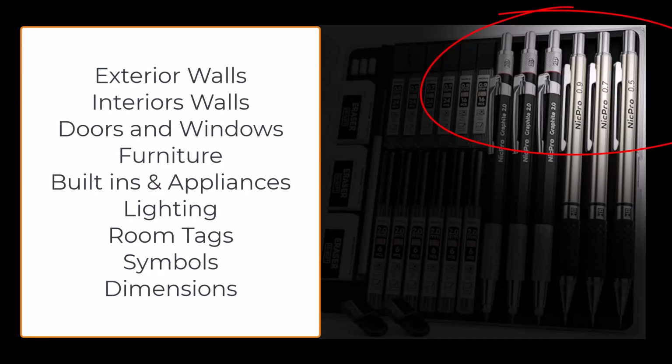What is most important about the pencil is that you are using the different gauges, which is the 0.3, 0.5, 0.7, and 0.9, and that you know what those lead types are as well. Some are softer, some are harder. They're going to be sharp, clean lines. So for instance, a 0.3, you want a sharper pencil because you're going to be creating very small, detailed lines. Those are the interior of a window, so the window pane, the actual glass.